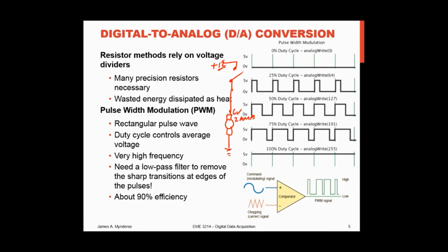And instead of seeing 6 volts here, I will see either 0 or 12, okay? And instead of 2 amps, I'll see 0 or it'll be something larger than 2 because I don't have that series resistance. We'll say, just for the moment, 4. But on average, if I were to do a time average, I can control that on-off rate up here such that I get an average equal to the 6 volts and 2 amps that I wanted to begin with, okay?